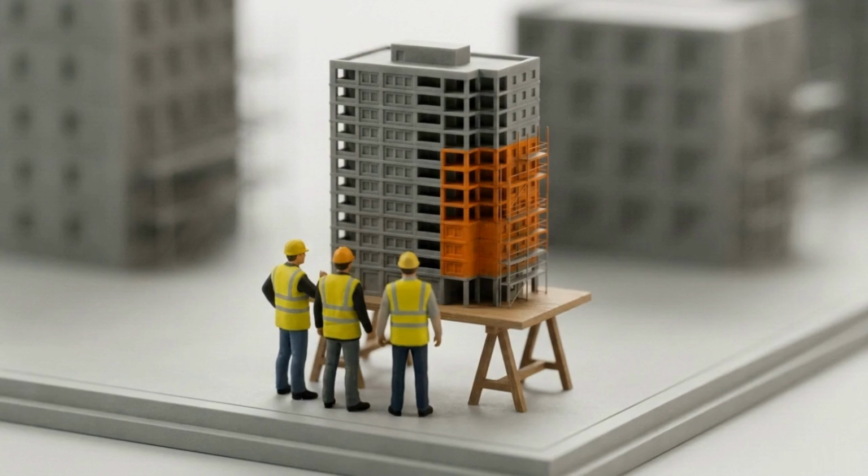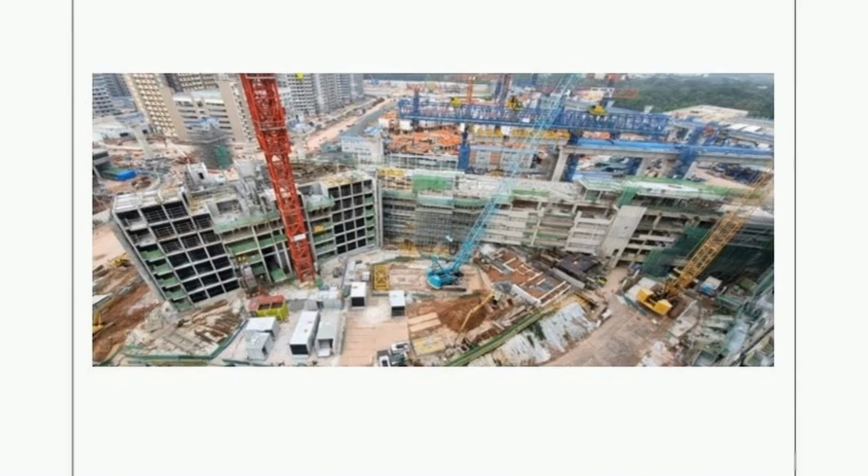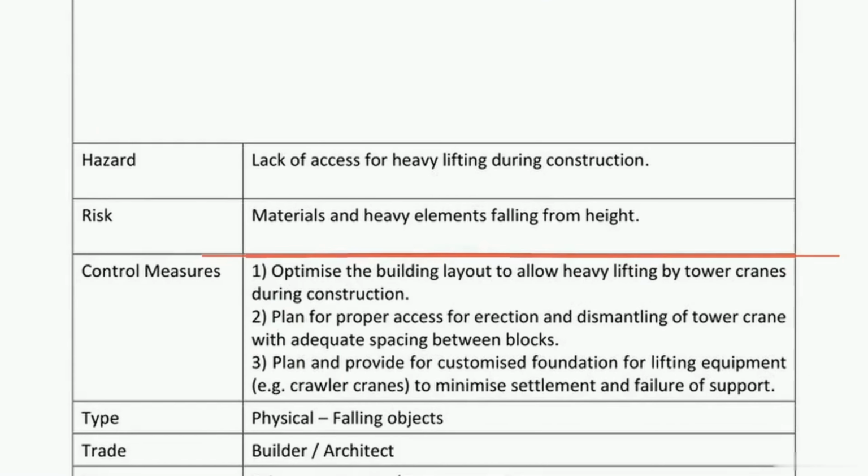By evaluating an engineering layout before work begins, we can identify embedded risks before any machinery arrives on site. This photo details a constrained layout. A crane between active blocks intersects pedestrian routes, risking materials falling into populated zones.